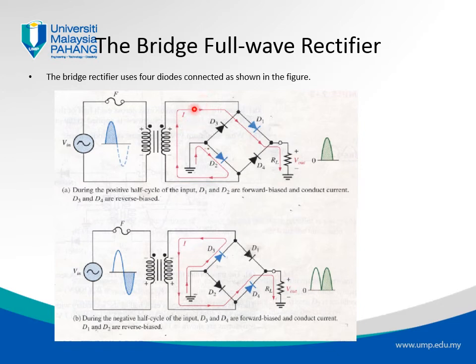In a bridge rectifier, we use 4 diodes that are mounted in such a position. The diodes are numbered D1, D2, D3, and D4. The numbers represent the two operating pairs with regard to the half waves of the input signal, the first half being the positive part of the waveform, and the second half being the second part of the waveform.